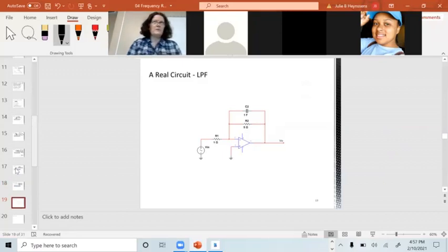What a low pass filter does is, let's say I have an audio circuit and the audio is coming from something like a radio or a Wi-Fi signal that has a lot of noise, a lot of signal in the megahertz region and in the gigahertz region. I want to filter that all out because it can actually get into my audio circuits and get beaten down in frequency, that's a real term, into the audio band and show up as these annoying buzzes. So I want to filter my circuit so I only hear audio.